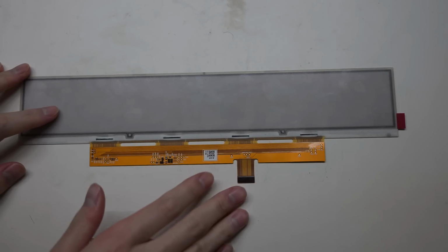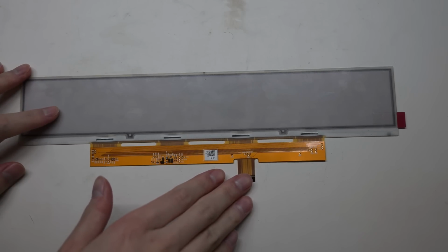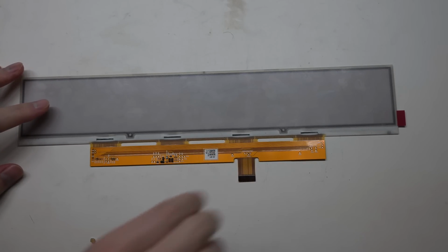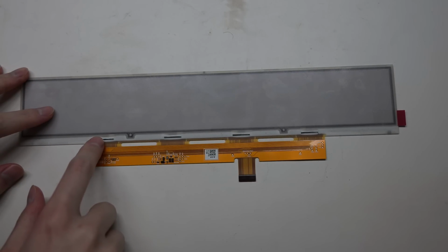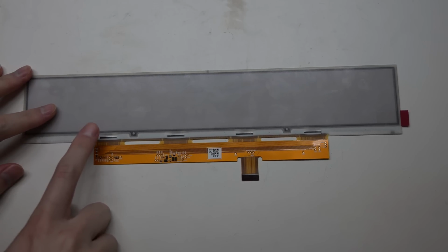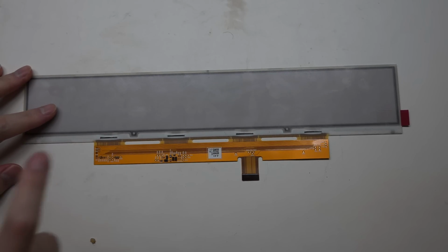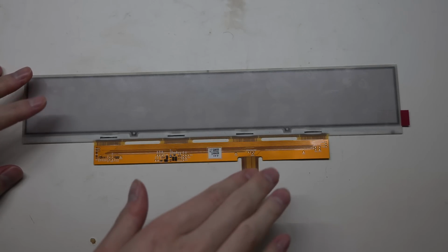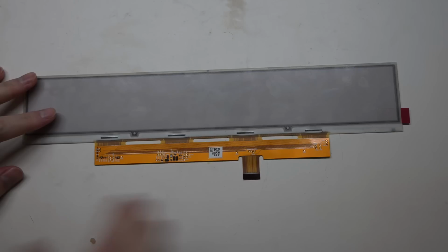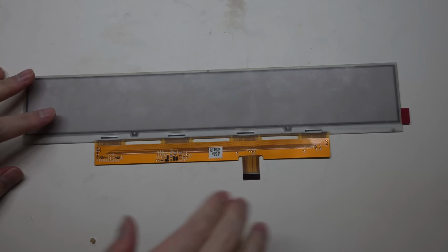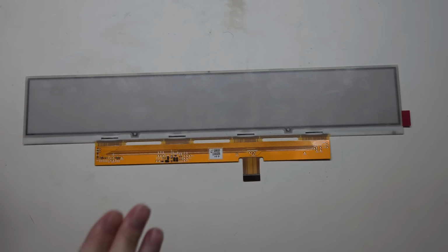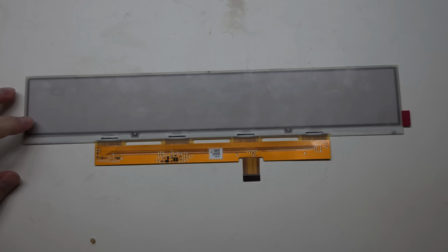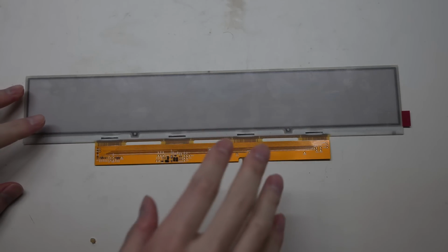One of the things I can do, if I know the pinout, is hook it up to a microcontroller. Usually these chips will have an ID register. By reading the ID register, I get to know what chip it is. But obviously I don't know the pinout here, so that doesn't work. Another way, assuming it's a write-only channel that I couldn't really read anything from, is to brute force it.